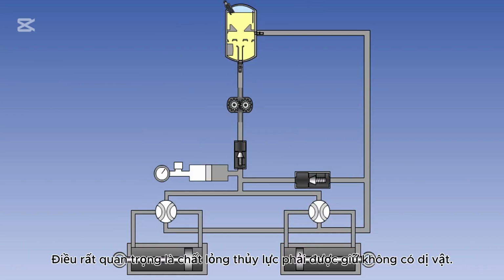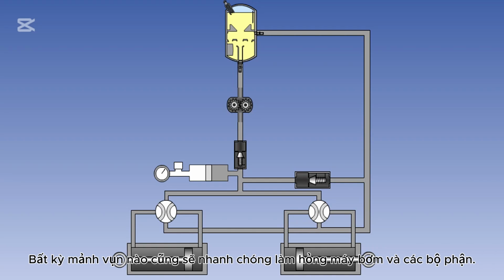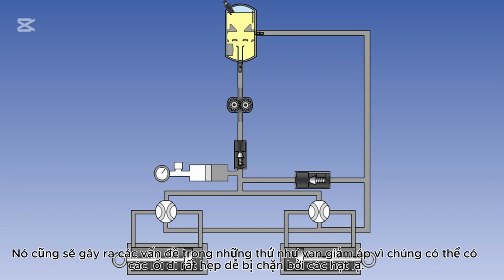It is very important that hydraulic fluid is kept free of foreign bodies. Any debris would quickly damage the pump and components. It would also cause problems in things such as pressure relief valves, as they can have very narrow passages which are easily blocked by foreign particles.